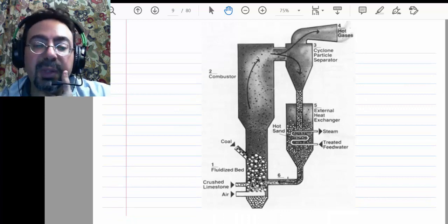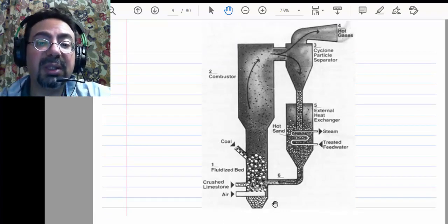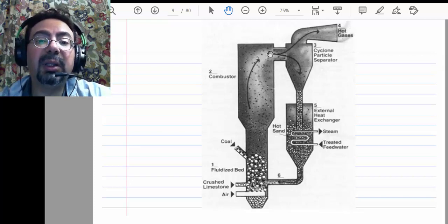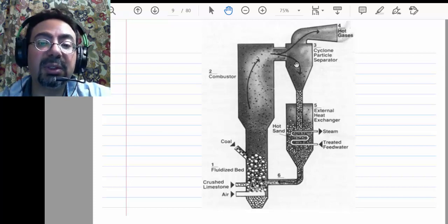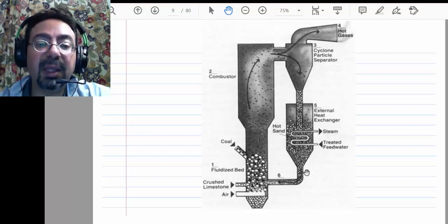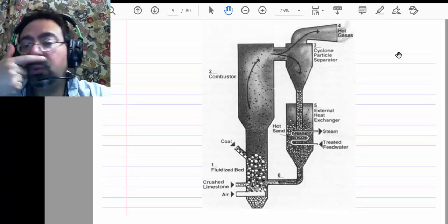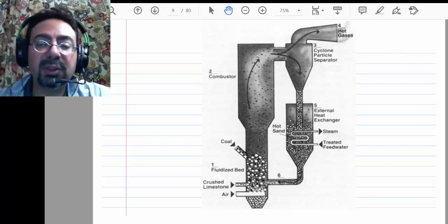In fluidized bed technology, the particles are floating while you are combusting them, and any particle that gets swept out and would make soot, you pull back with the cyclone separator and refeed it again. Only the hot gas is allowed to go to the furnace, to the rest of the boiler, to make the water boil for us.